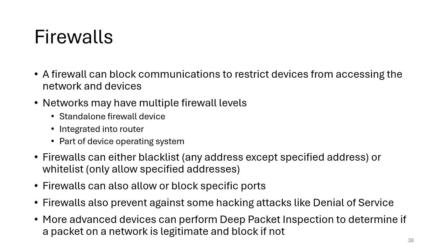But it's not normally enough to have a single firewall. We're seeing evolution of how attacks work. It could be that the attacker gets into your network and does something on a computer that's inside the firewall, and then controls that computer inside the firewall to send your message using port 502. So it's not enough to block port 502 at the firewall. You also need to block the other attempt and potentially block internal communications.